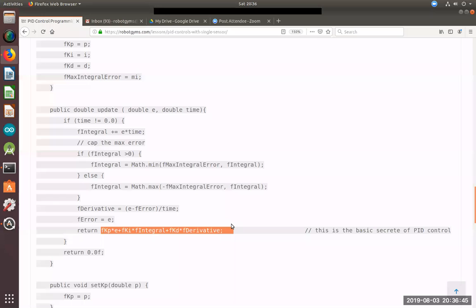If you want to apply half of the power, then the motor alternates power. 50% of the time you send power, then drop to 0, then send power again. Basically, half the time you send power, half the time no power. This is how the robot controls it. They are not controlled by voltage; they are controlled by how frequently they send out the power. Got it?